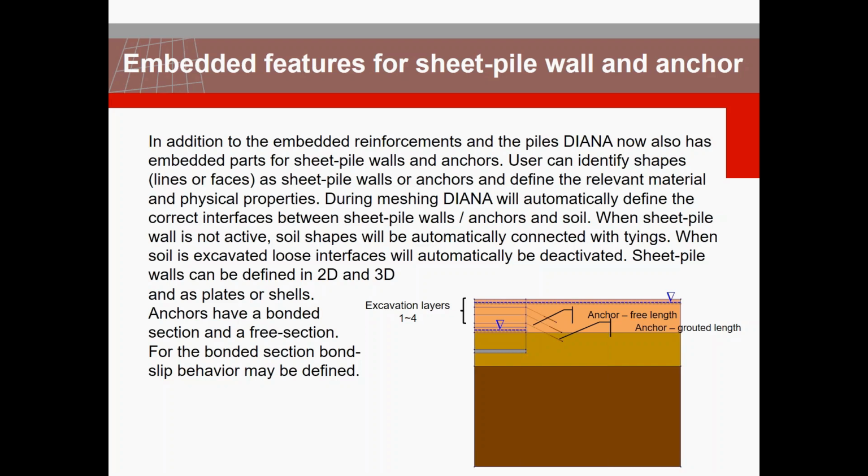If there is an interface definition, so there is a soil structure interaction, this interface can be automatically generated by use of one R factor that we can explain later. And when you want to go for initialization, when the interface and corresponding sheet piles are not active, the continuity in the soil layers is guaranteed, and you can nicely proceed with the stress initialization.